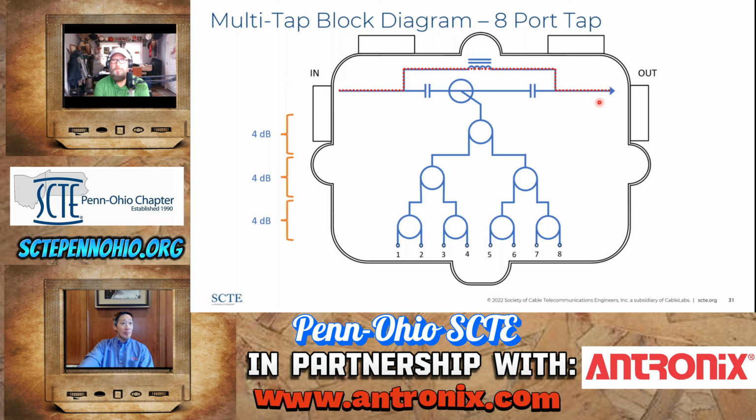A certain percentage of the power goes out here. So if you have more loss or less loss going down the tap port, you're really affecting your insertion loss. So the higher the tap value, the lower the insertion loss. So higher tap value means more loss through here, but it's lower insertion loss. So if you're changing a tap, you do want to make sure you change to the same value tap.